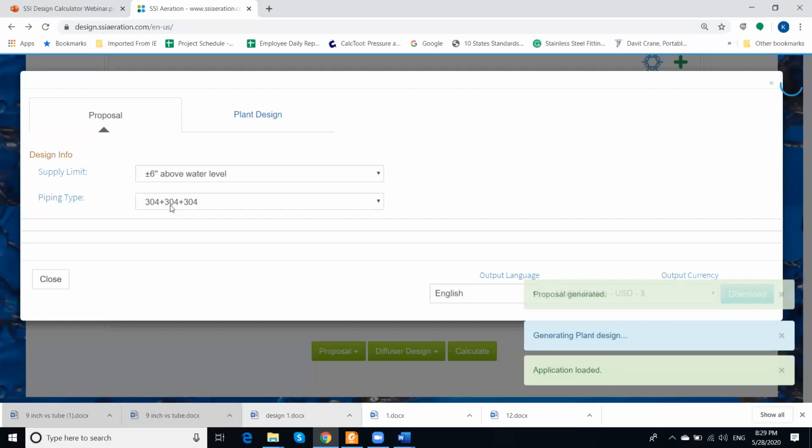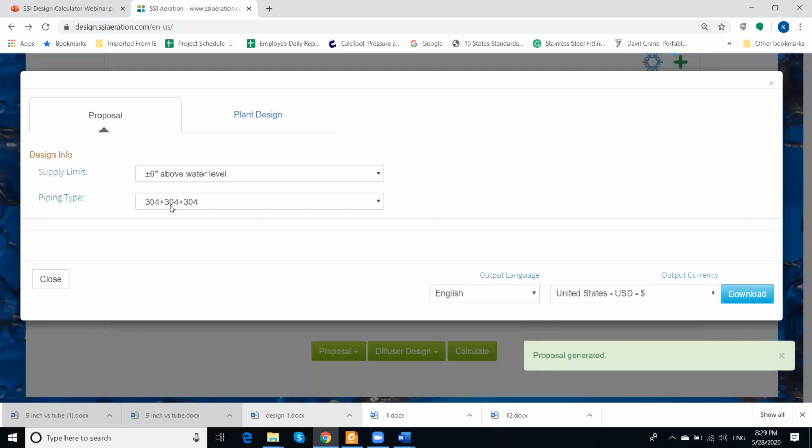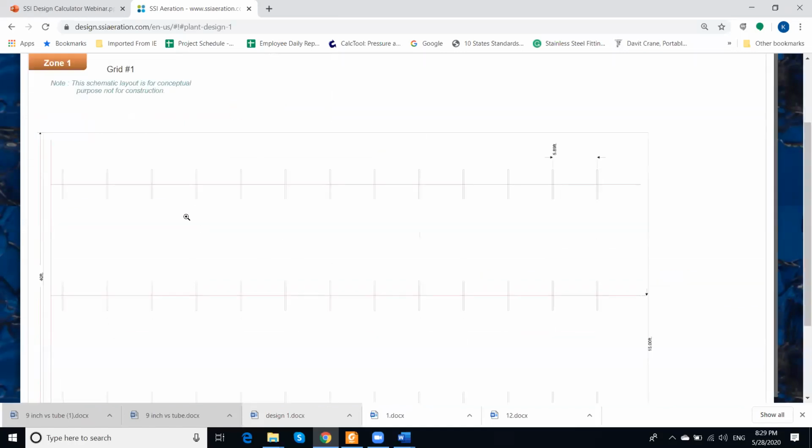Alpha will change based on the mixed liquor suspended solids, so that is already kept in the code. Automatically, if we change MLSS, alpha will change. In the same way, we kept elevation versus barometric pressure. So people need not bother about going again to search for the alpha value or the barometric pressure, etc. So this is the wideband option.